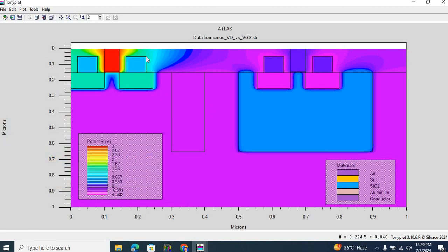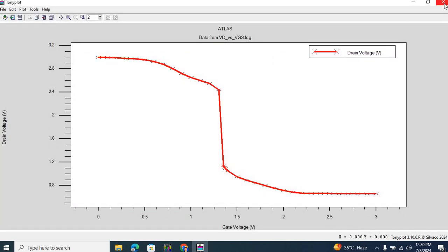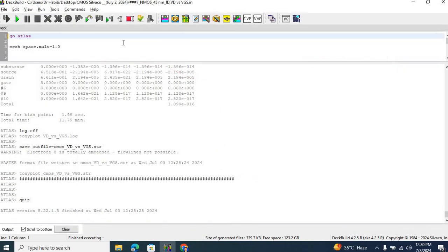Okay, so the gate voltage is now high, and we have connected the source where we have made a channel. We created a channel connecting the drain with the source, and when the input is high, the drain is connected to the source, so the output is going to switch from high to low. So this functionality of the CMOS inverter is verified now with this code.